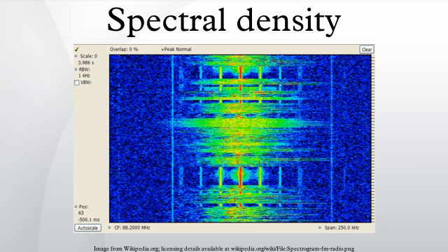Related concepts: most spectrum graphs really display only the power spectral density. Sometimes the complete frequency spectrum is graphed in two parts, amplitude versus frequency and phase versus frequency. The original function cannot be recovered from the amplitude spectral density part alone. Information about the phase is lost. See spectral phase and phase noise. The spectral centroid of a signal is the midpoint of its spectral density function, that is, the frequency that divides the distribution into two equal parts.